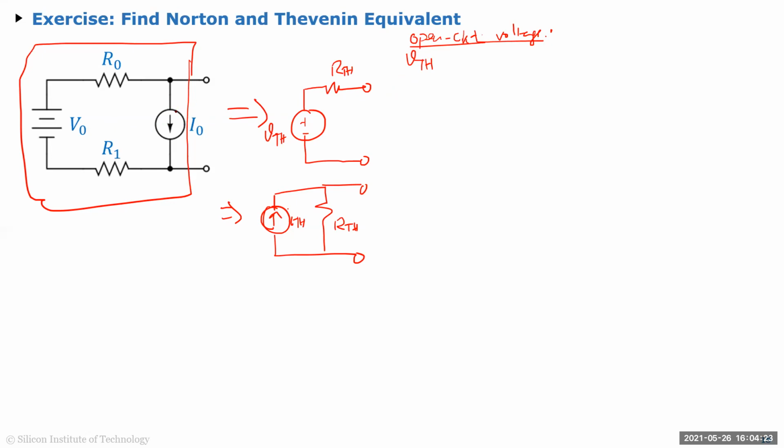So when the current source is off, which is open, then this voltage is V naught, right? And when the current source is on and V naught is shorted, right? Independent sources is zero, means voltage source is short here. This is shorted. Then because the current is in this direction, then the voltage is I naught. So VTH is equal to V naught, that's your first superposition value, and then minus I naught times R1 plus R2, correct? So that's your VTH. And RTH,